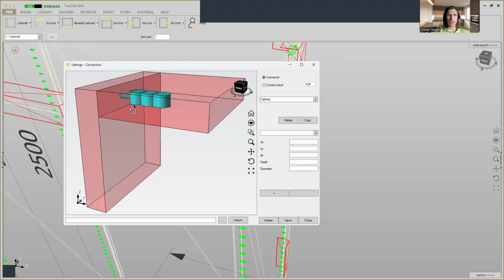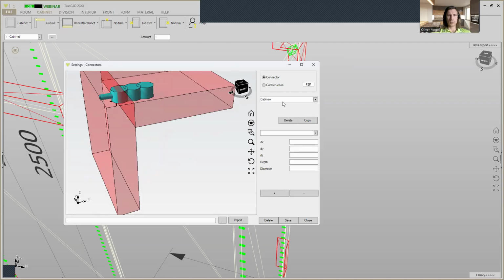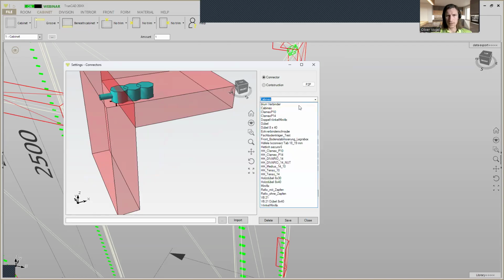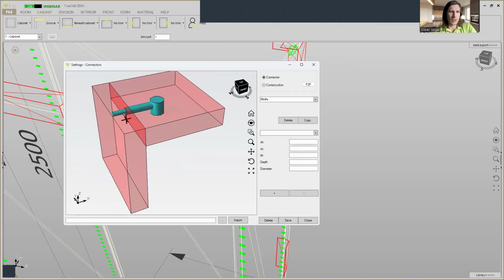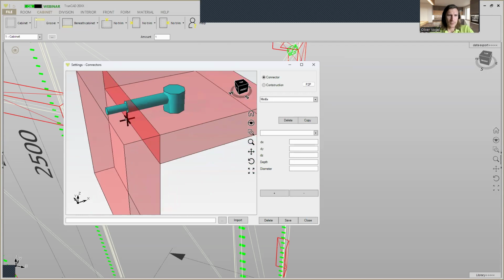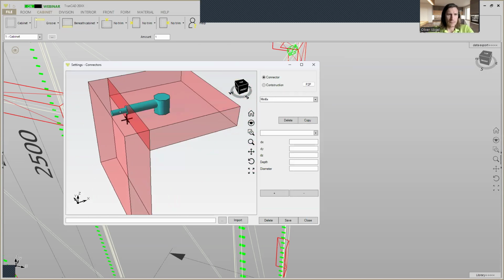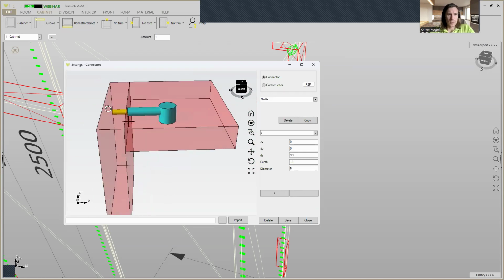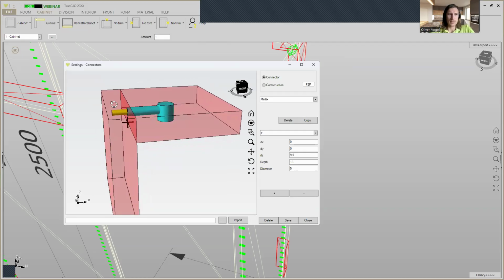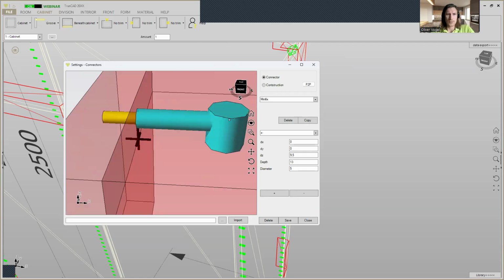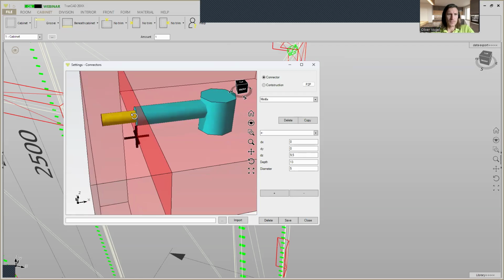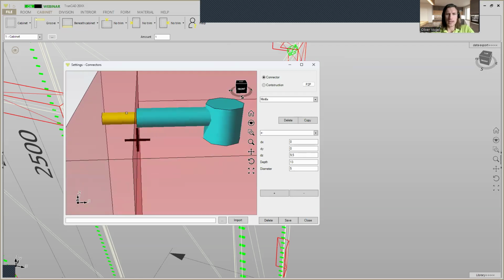I show you on the case of the Cabineo, or let's do the minifix. So the minifix is here, and here we have the reference point. And if we click here on this drilling, we see the drilling pattern of the minifix, and that is here the drilling, the drill direction of the drilling for the side.